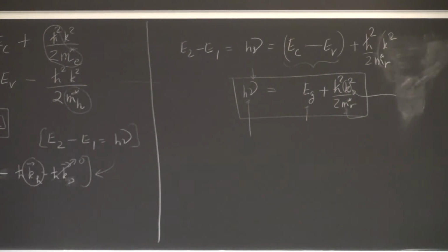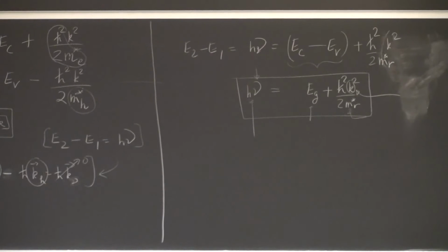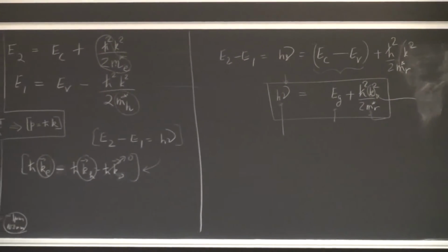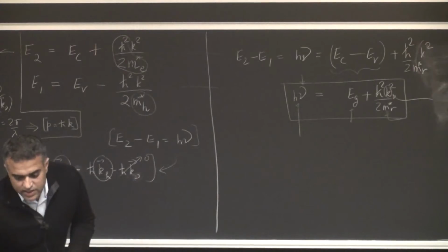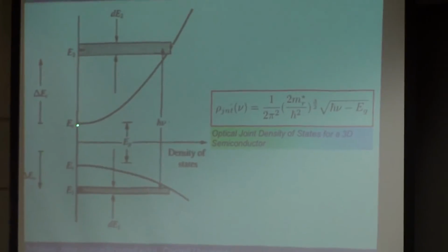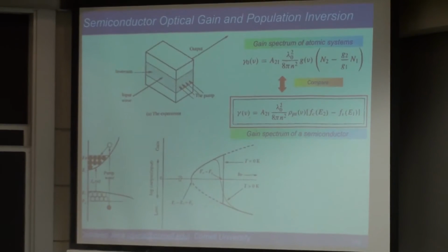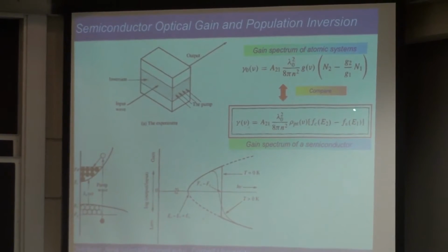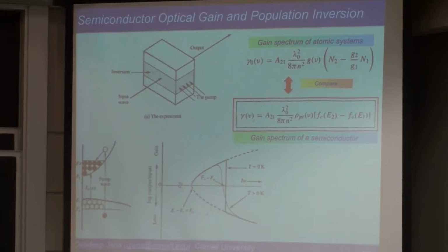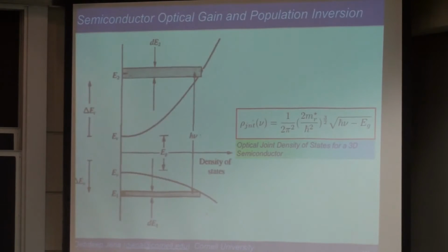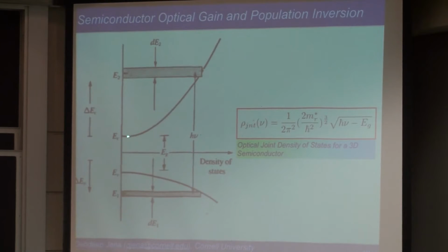So is this result true regardless of doping? Very good question. This result is actually independent of doping. What we'll see is that the doping is what's going to control things like the occupation functions and all that. To first order, if you want to get into too much detail, even this changes when you dope very heavily: you develop band tails and all that. But we don't need to be concerned about that at this point. Yes, this result is independent of doping.